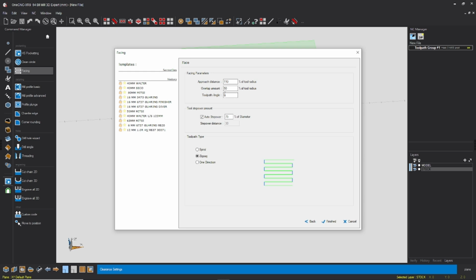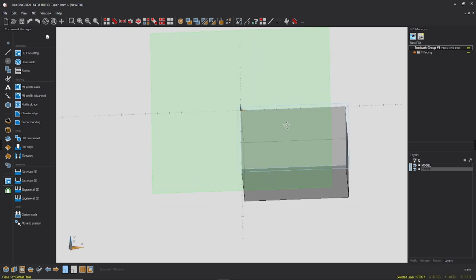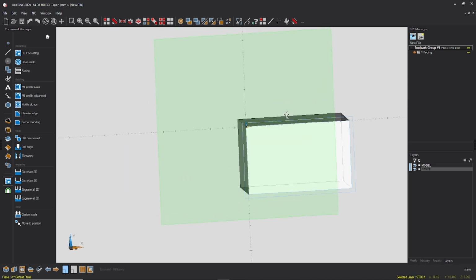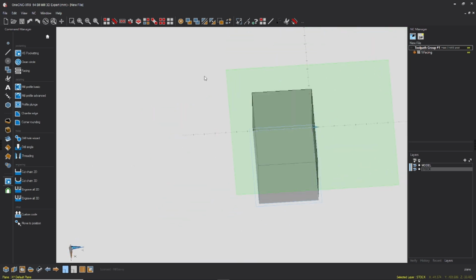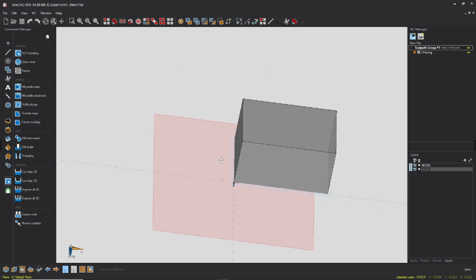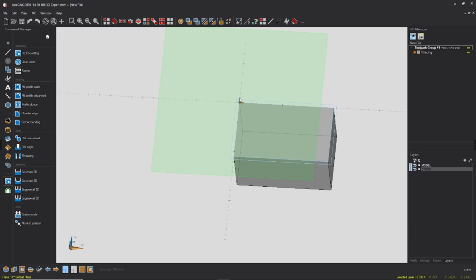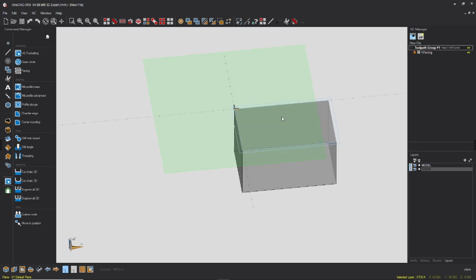See, this is here if you wanted to cut in your Y axis rather than your X axis. So for instance, X is left to right or right to left; if you want to go front to back, then you can literally put 90 in there. There's a few reasons why you might do that. For instance, if you're doing something as a 5-axis part and you'll hold your vices here, and there's something in your way over here, like your stop or something, you might not want to travel this way, and you might be safe to go forwards and backwards. So there's times where you need to rotate it.